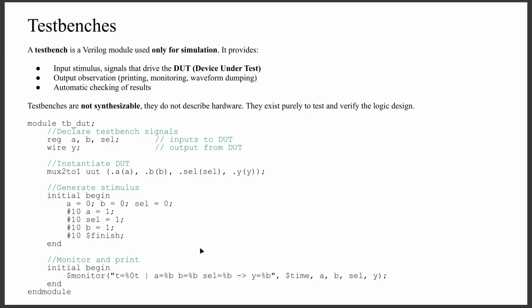Test benches. A test bench is a Verilog module used only for simulation. It provides input stimulus, signals that drive the device under test, output observation, printing, monitoring, and waveform dumping, and automatic checking of results. Test benches are not synthesizable. They do not describe hardware. They exist purely to test and verify the logic design.